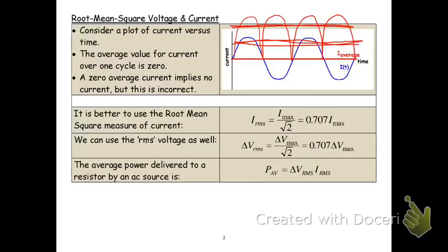So let's have a look. What we did, we squared it, and we rooted it, and we meaned it, and we rooted it. And so they call this the RMS, the root mean square. I don't know why they don't call it the SMR, because that's the order you did it in, but it's called the RMS. The RMS is 1 over the square root of 2, which is 0.71. So I remember it as 71% of.